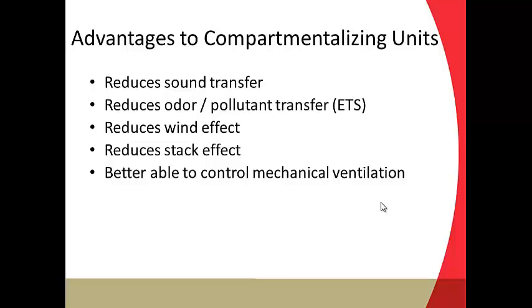Allows you to be able to control mechanical ventilation much better, certainly also. If you do a really good job at tightening the outside walls and don't pay attention to the walls between units, you're certainly going to have indoor air quality problems, and it's going to be hard to control the stack effect and wind effect and mechanical ventilation in the building.